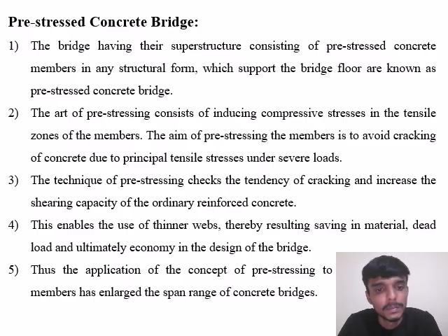The technique of pre-stressing checks the tendency of cracking and increases the shearing capacity of ordinary reinforced concrete. This enables the use of thinner webs, therefore saving material and dead load, and ultimately giving economy in the design of the bridge. Thus, the application of the concept of pre-stressing to bridges and bridge members has enlarged the span range of concrete bridges.